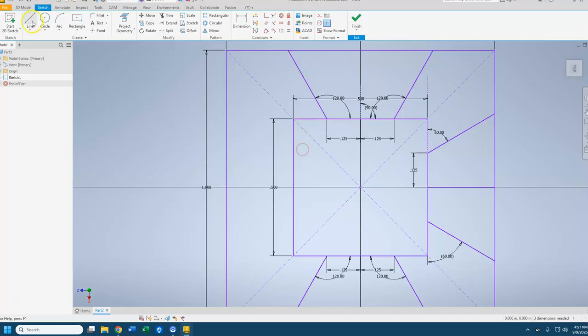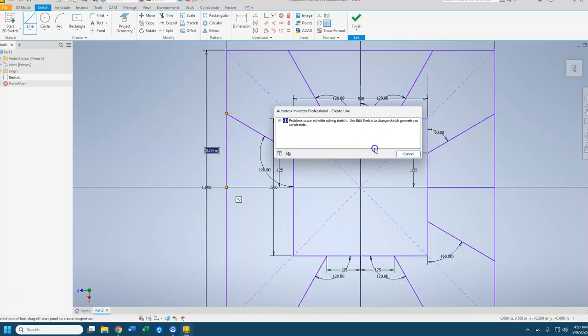So we're going to come over here, we're going to do the same step we've been doing. I'm going to try really hard to just teach you as many different ways to do things as I can. So notice it's considering this to be 0, so I need to take 90 and add to that to make that 120. Tab 120. Oh, did you notice I accidentally added it, I clicked out here, I didn't lock it here, so what I'm going to come in and I'm going to trim and I remove the extra. Then I'm going to start my line right there and add to it.